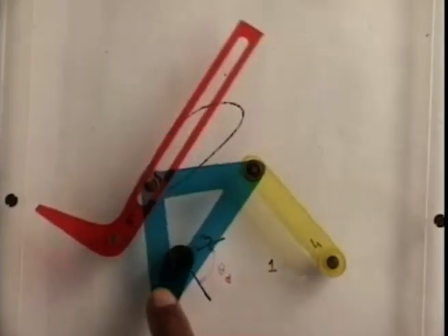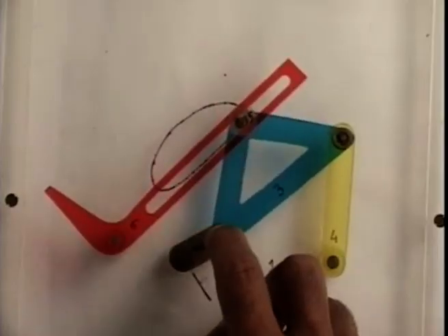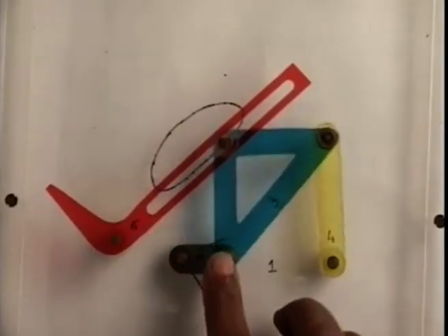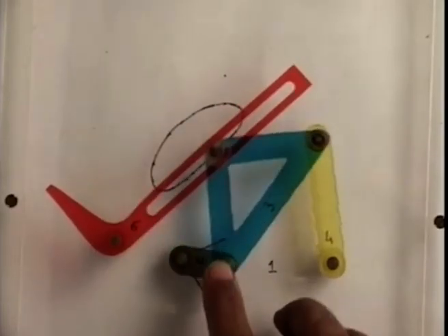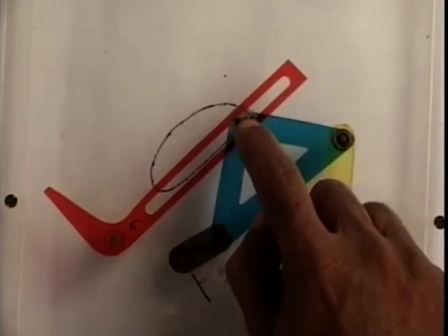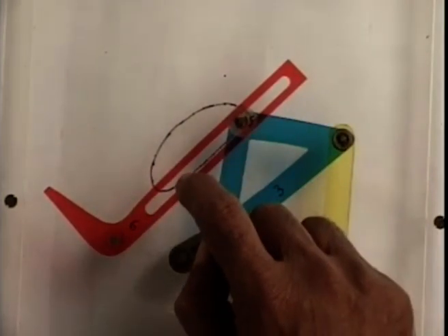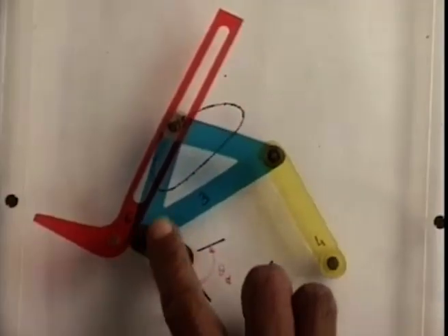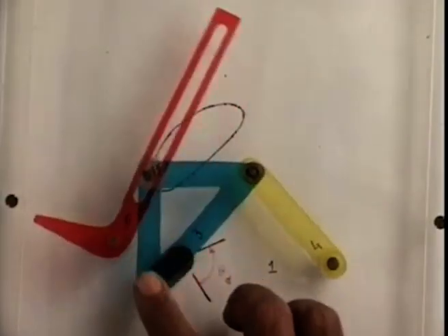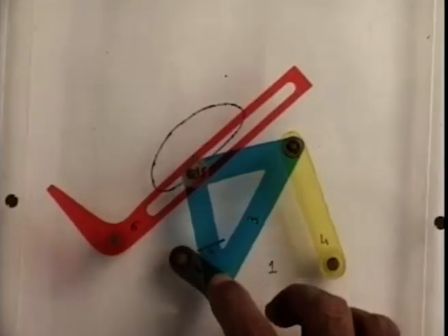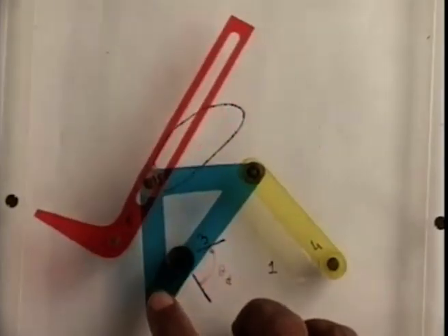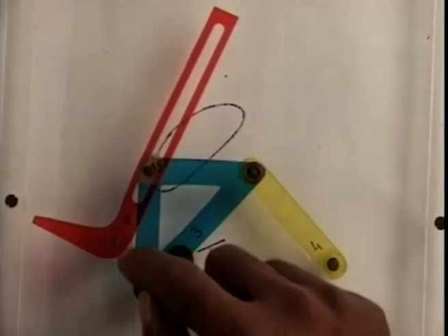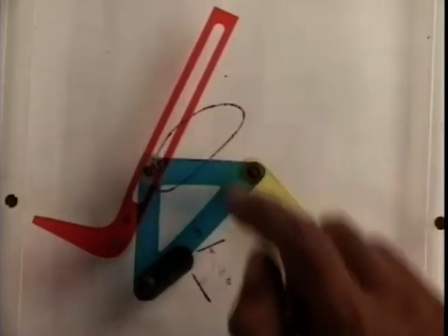As we give continuous input rotation to this crank rocker linkage, we should notice that during this interval of the rotation of the crank, the output link hardly moves, because this coupler point goes along a fairly good approximation of a straight line. And as soon as it comes out of the straight line portion, the output link starts moving, and this is the extreme position of the output link when this line becomes tangent to this coupler curve.